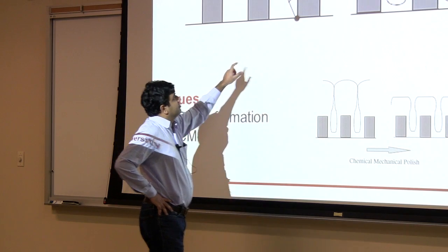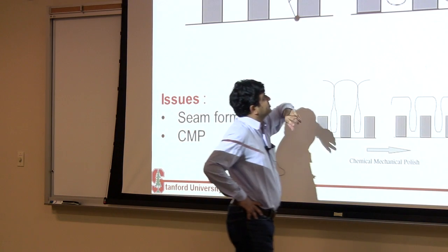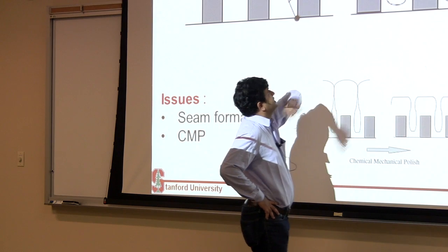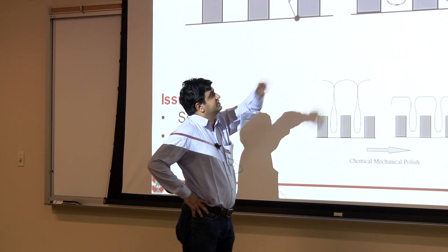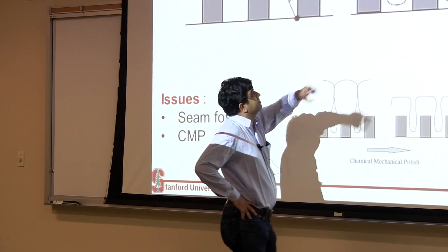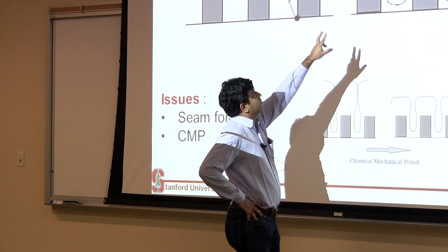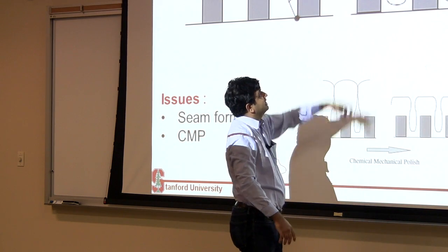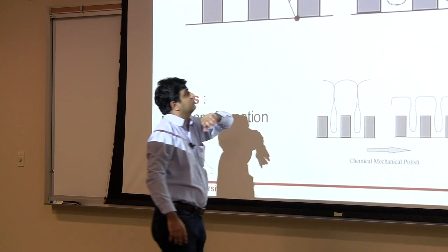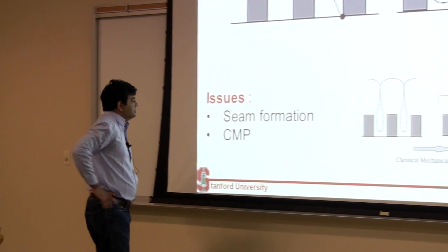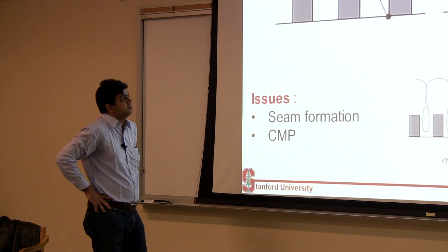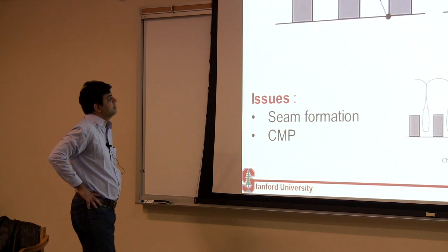So by the inherent nature of your CVD, you get closure in your profile. If you just keep going along that path, you essentially get a closure between these two fronts, and these two fronts on the top meet, and they leave an air gap in between. This is used by almost everybody who uses air gap.